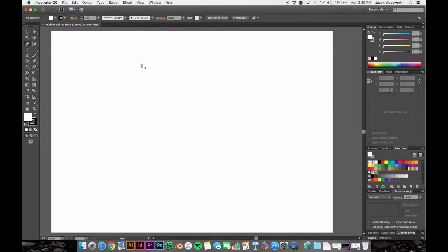and show you another part of the pen tool, which is putting curves within your anchor points. So if I click once and I click again, now let's say I click, hold the mouse down and drag, you can see it's starting to create a curve in the previous line that was made, but it's also going to set you up for another curvy line.